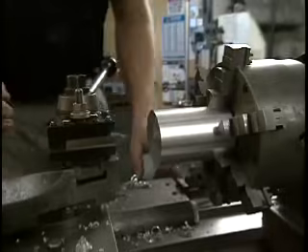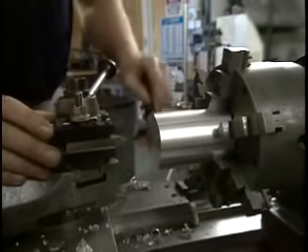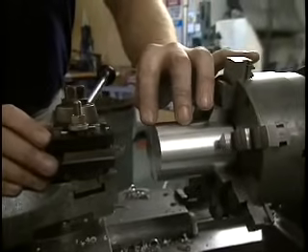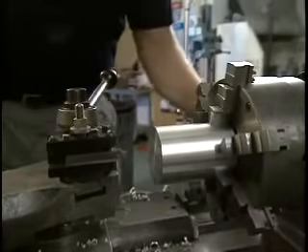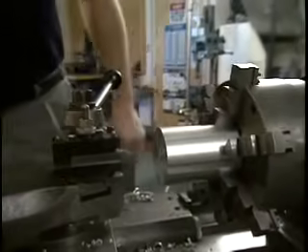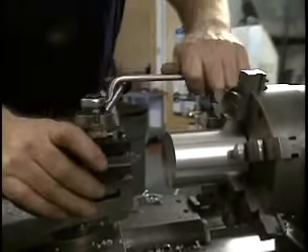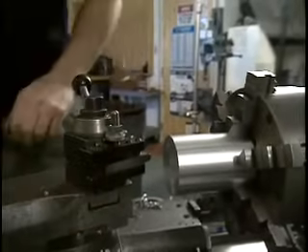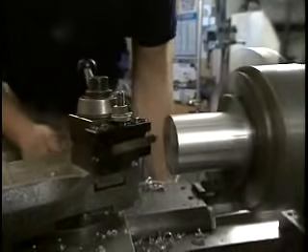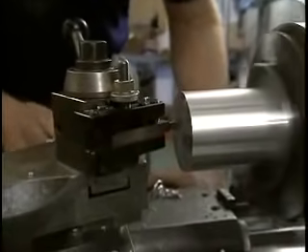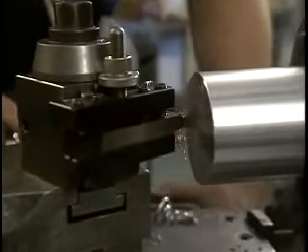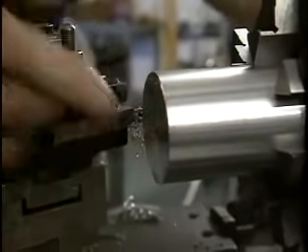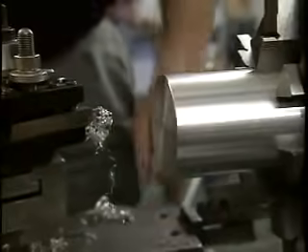The last operation involved in facing a part is to break the edge. You produced a knife edge here. It's very dangerous. There are a couple ways of dealing with this. One way is to turn the tool and just bring the tool into contact lightly with the edge, breaking the edge and making it safe. This can also be done with a file.